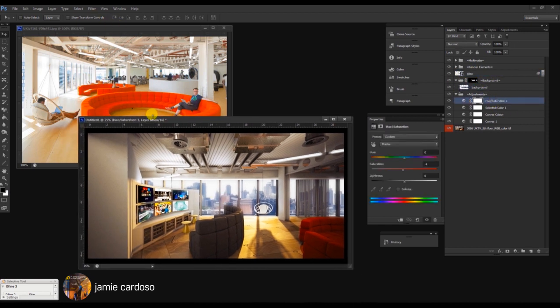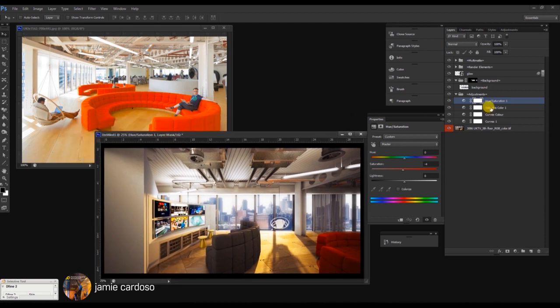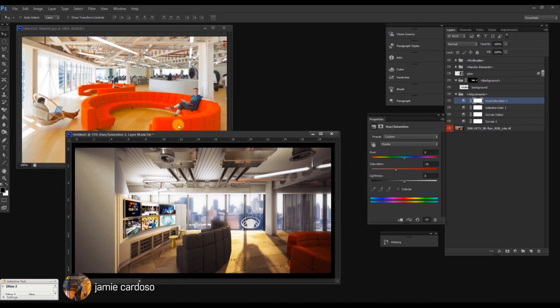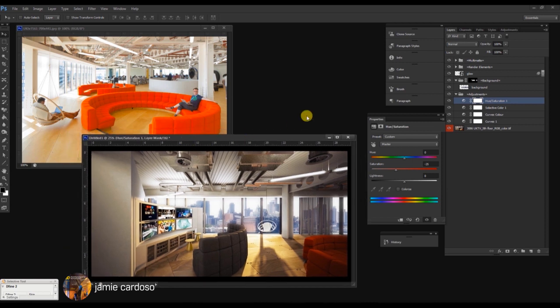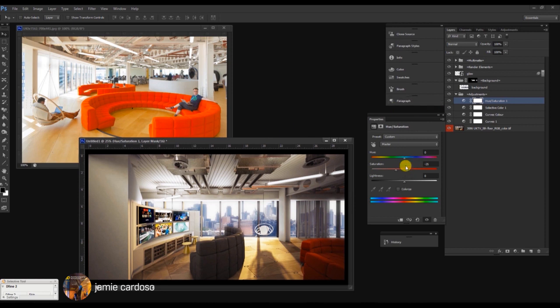The photo looks a bit more desaturated than ours, so we're just going to desaturate it a bit further, so it looks a bit closer to this one, even though most of the environment in the photo is desaturated, but the chairs, or the sofas rather, seem to be quite vivid. So we're going to use the multi-matte later on in order to make that a bit more vivid.